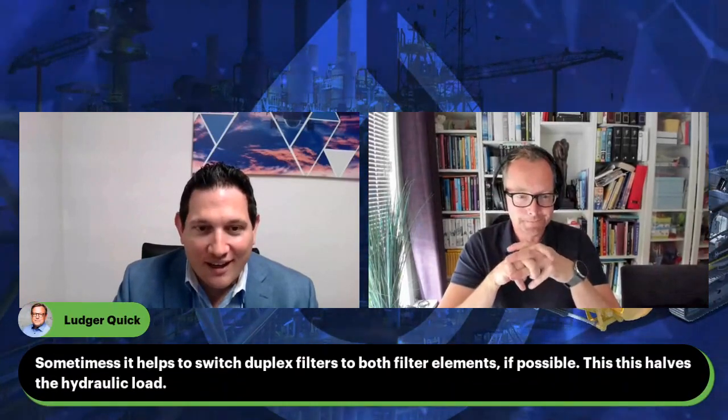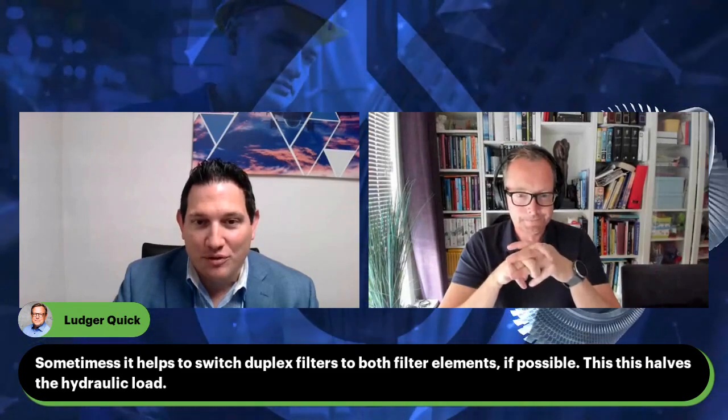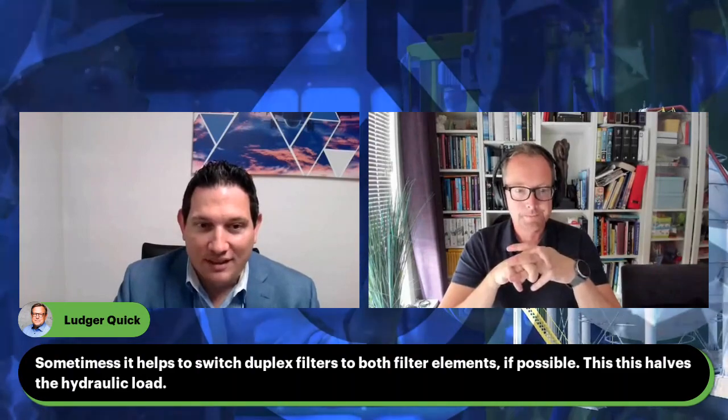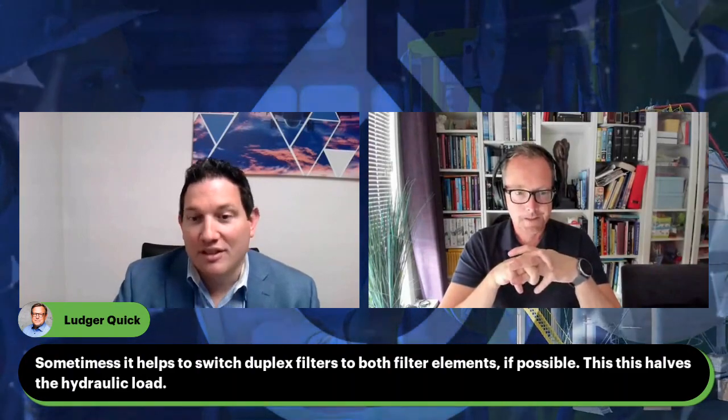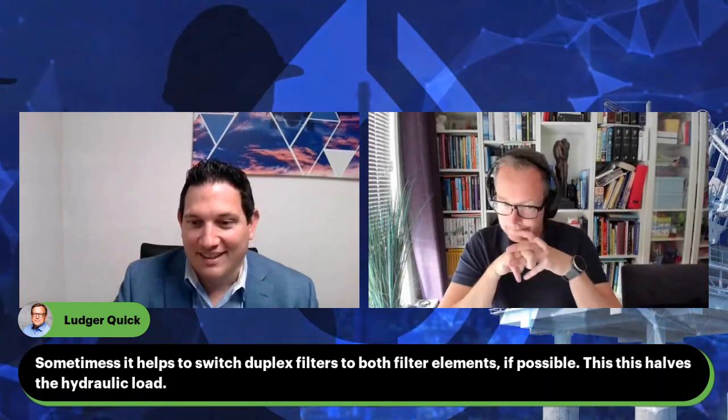We have a comment from Rolf, who says thanks, this is helpful. So thank you, Øystein. And then Luger is making a comment here, saying sometimes it's helpful to switch duplex filters to use both filter elements if possible. Yeah. As I said, that helps a lot. Yeah, takes the load out.